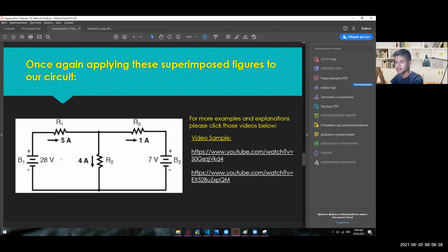So here is also the final circuit flow of current. Okay, so we have 5 amps right here, 1 amp right here, and then 4 amps right here. So it is now obvious that this 28 volt will dominate this 7 volt right here, wherein this 7 volt is being charged by this 28 volt right here.